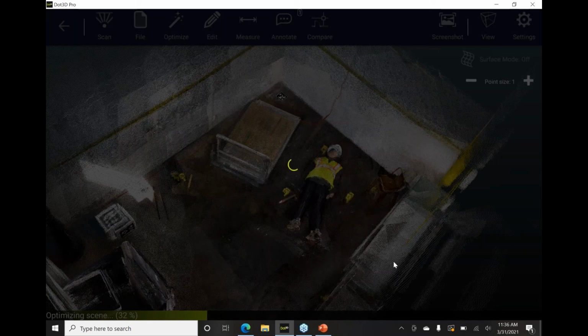The best practice for that is to take a quick length, width, and height measurement, and that will really, really tie down your data. All of these workflows, even that basic April tag workflow, are totally optional. You don't need any targets at all to create a data set like we just did, but they're very easy ways to get that added confidence and accuracy, especially for larger area scans. Those parallel plane constraints, so anytime we flag a level surface as being parallel to itself or to another plane, those are automatically being accounted for during this optimization.